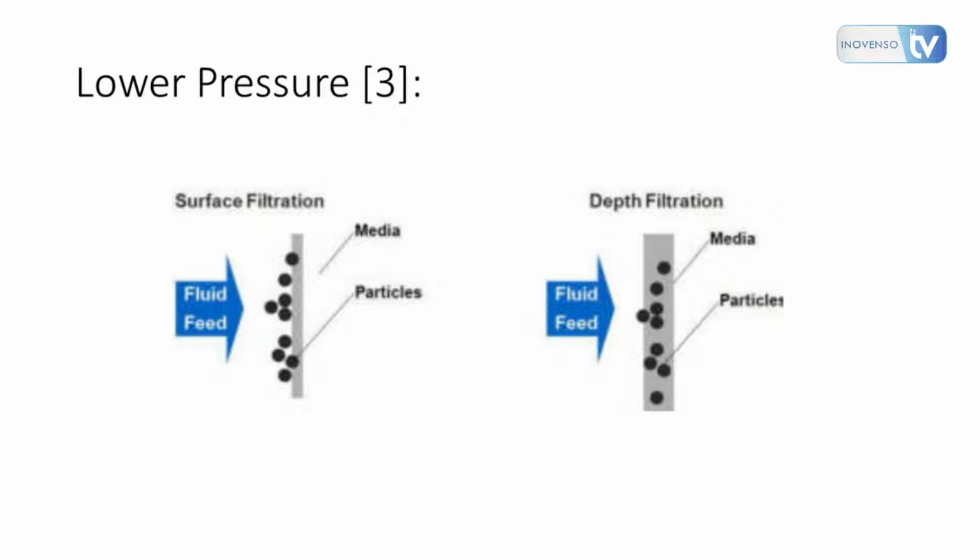So this is a picture that shows surface filtration and depth filtration. It just gives a better idea of what it looks like. You see the particulate matter stopping on the surface and not seeping inside, which is what we want, and which is what you see with nanofiber air filters. Whereas in depth filtration filters, all the particulate matter gets stuck inside, okay? And that's causing blockage of pores. When you have such issues, they need to be quickly discarded. Otherwise, the pressure drop will increase gradually because of the blockage.